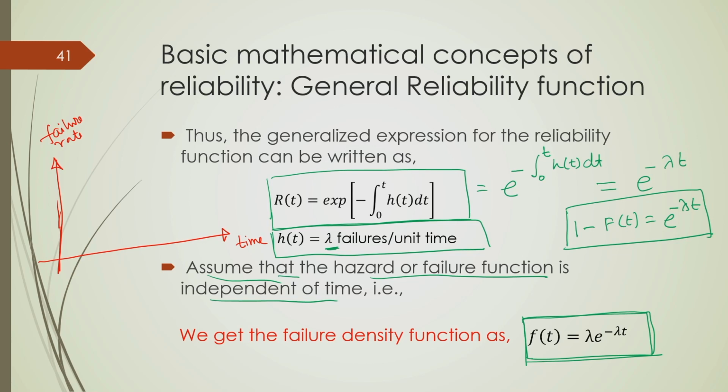Okay. We will see there are two components which basically influence the failure of any particular equipment. One component is fast decreasing like this with time, and it has an initial higher failure rate, and as t goes to infinity, or t very close to a high value of time, it comes out to be 0. That is basically called the infant mortality rate.